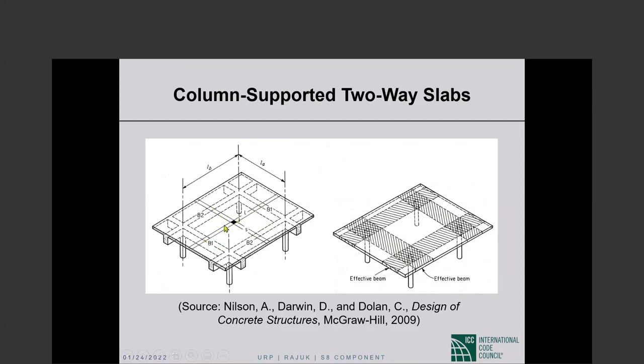Now the 40% of the slab loads that are transferred by bending in the long direction, those loads are transferred to beams B1, which span in the short direction. Okay, so 60% of the load on the slab is transferred by bending of the slab strips spanning in the short direction, and the remaining 40% of the load on the slab is transferred by the beams bending in the short direction to the supporting beams.